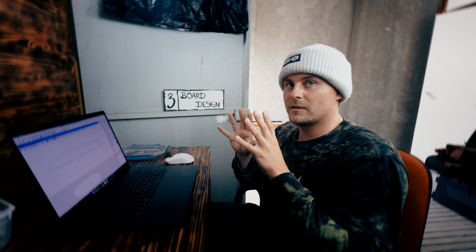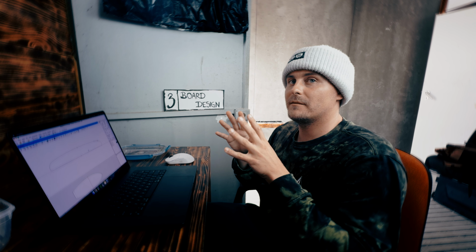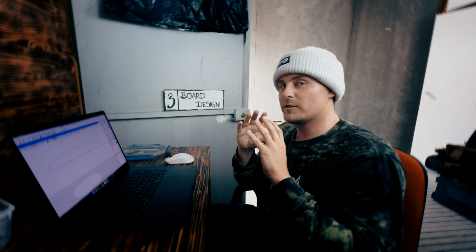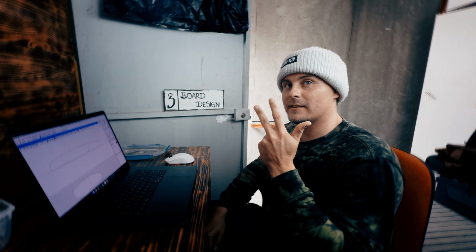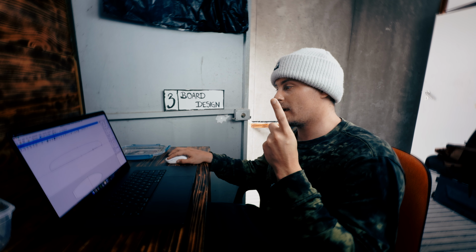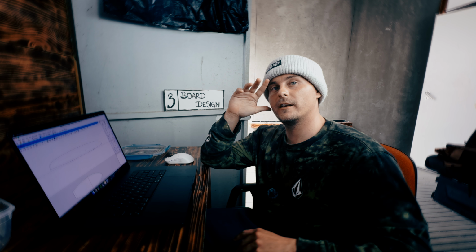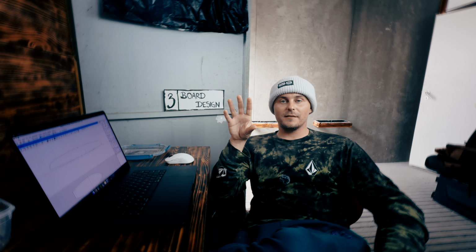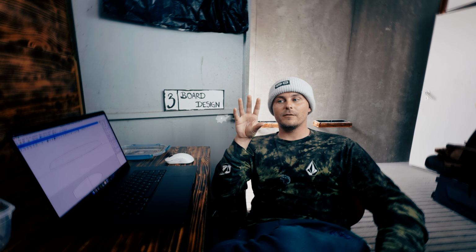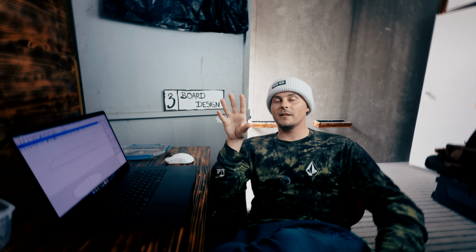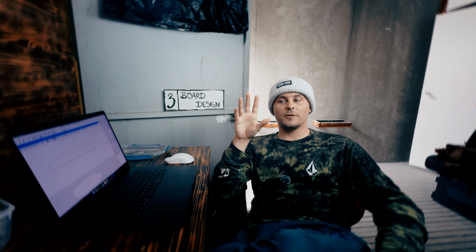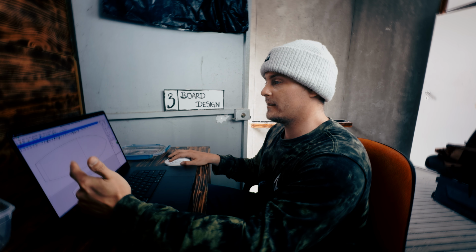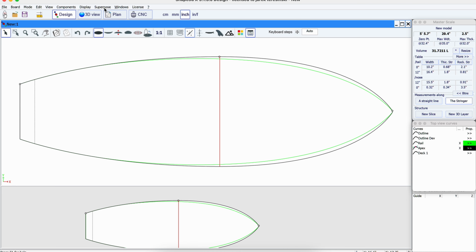And yeah, when we're really shaping this, I'm gonna give some, let's say, magic numbers that just work, and also what I like and what I don't like. Stick to the combination of these 3 things, which is the single concave, the double concave and the V. And based on these 3 types of bottom contour, you can actually design bottom contour for any type of shorter boards, which is not the mid-length, but short board, performance board, groveler, fish, hybrid, you name it, you can design it.